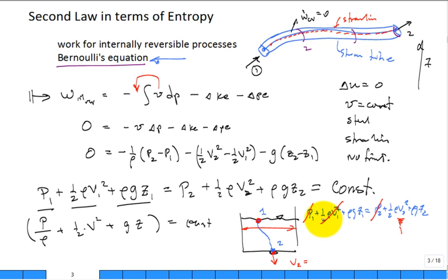So what we find is that the height of the water level of the tank is just Z1 minus Z2, isn't it? So what you have is 1/2 rho V exit squared equal to rho G times Z1 minus Z2. Cancel the rhos. And we're going to get that the exit velocity is equal to the square root of 2GH.